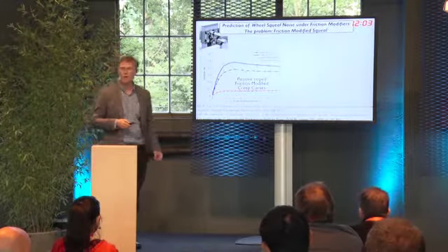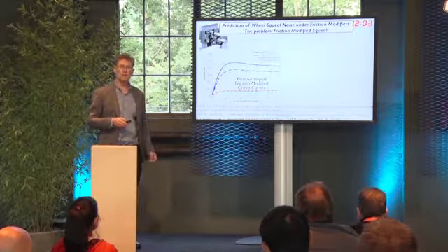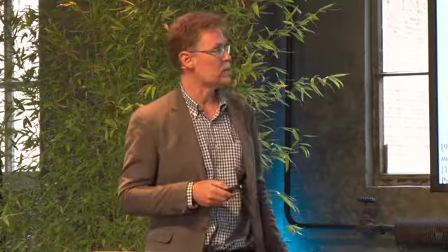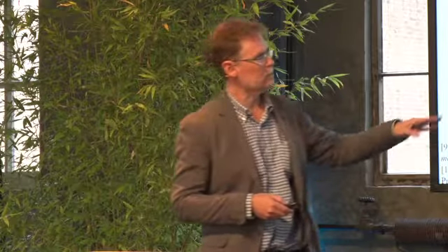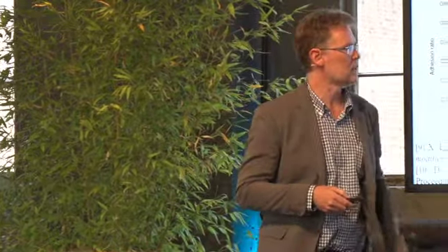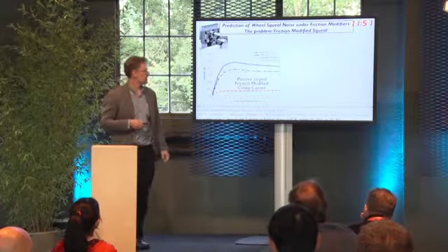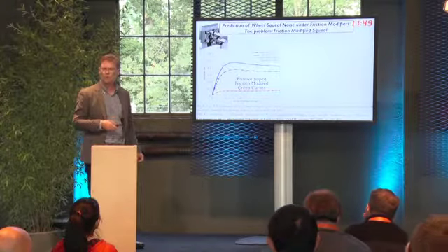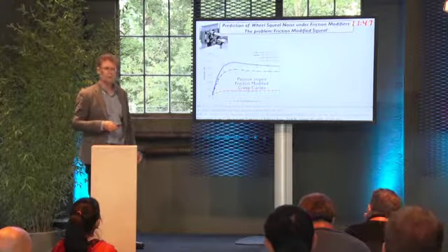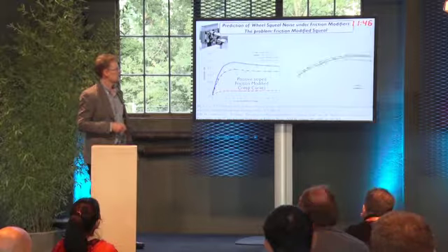Friction modifiers have been successfully used to reduce the sound pressure level of squeal noise, typically because they get rid of this negative slope, but they don't always eliminate wheel squeal.